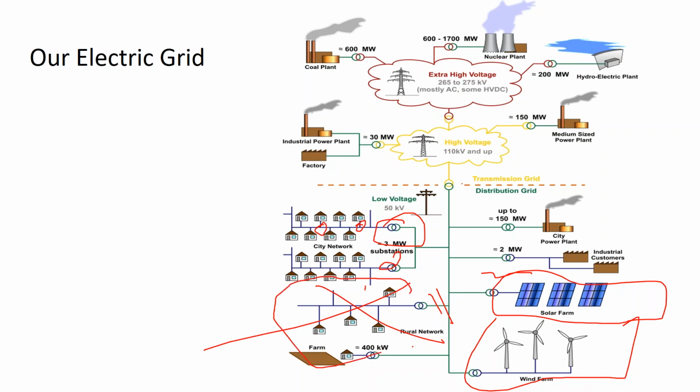One problem is if there's too much solar on this distribution circuit, some of these distribution transformers are not able to be backfed. And so what happens is they read the electricity flowing in the opposite direction as a grid failure, and then they shut off power. So in a rural area, the utility's not being unkind if they say, well, we already have too much solar outflowing onto the grid. And with that, you would do something like the SMA inverter has, a zero export mode where you don't output power onto the grid, or that grid assist configuration we talked about. Either one is essentially equivalent.